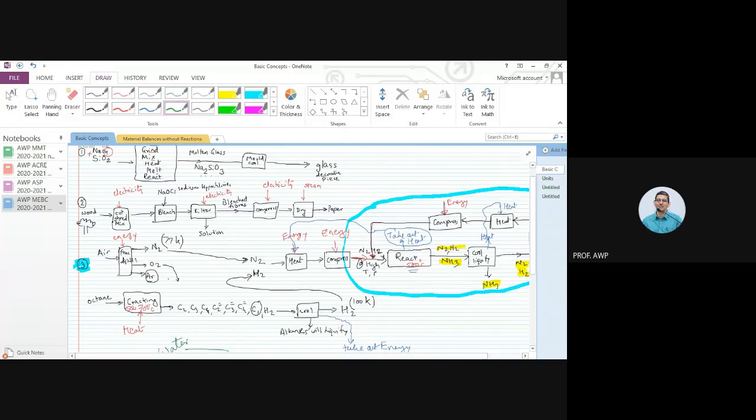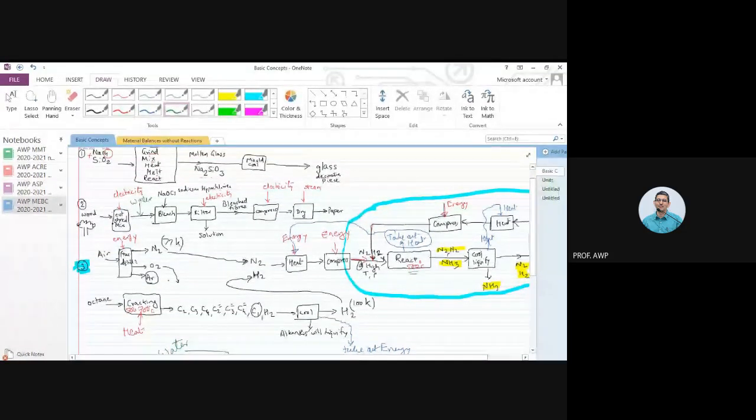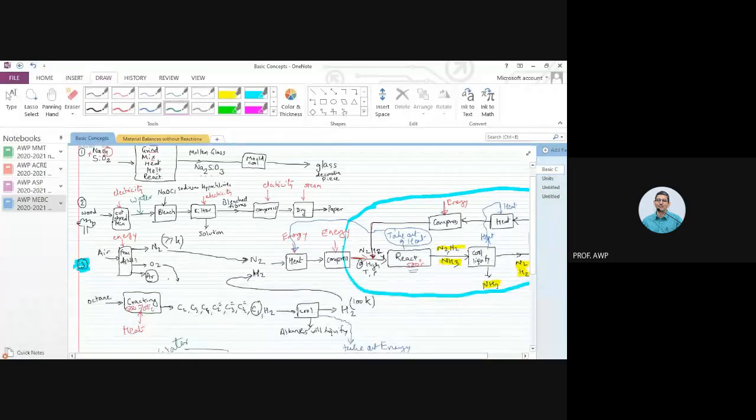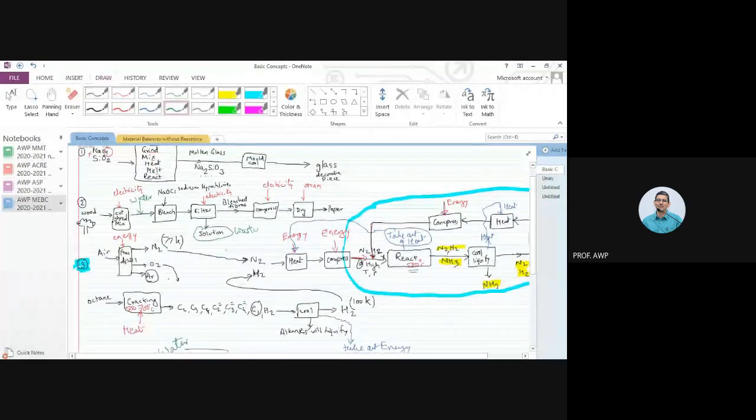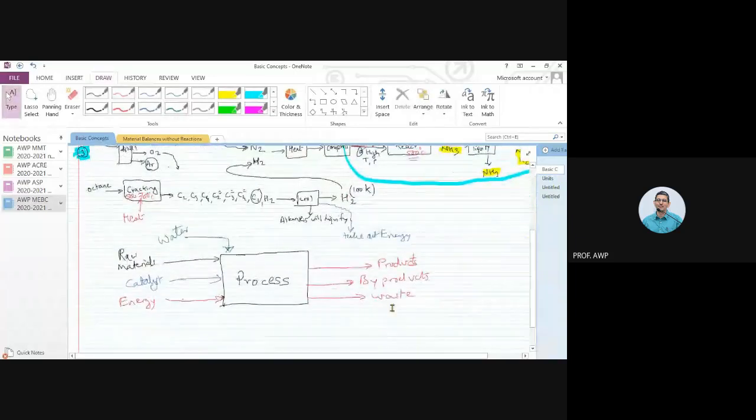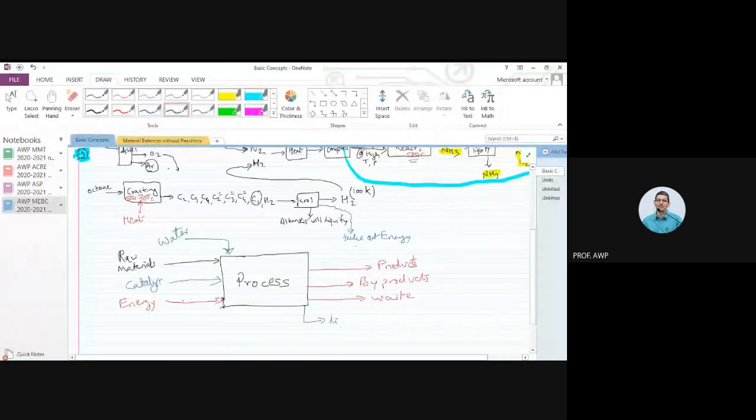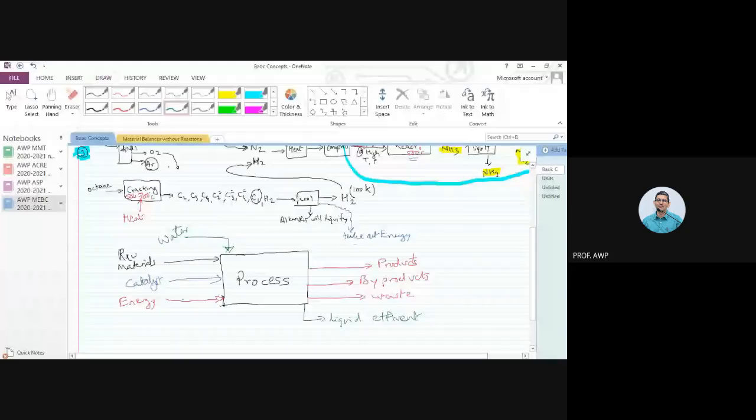All these wood fibers that you have shredded, you need to add water so that it becomes a pulp. Then you add your hypochlorite, then you do bleaching, then you filter out. So whatever water you have put in goes as a liquid waste, liquid effluent.